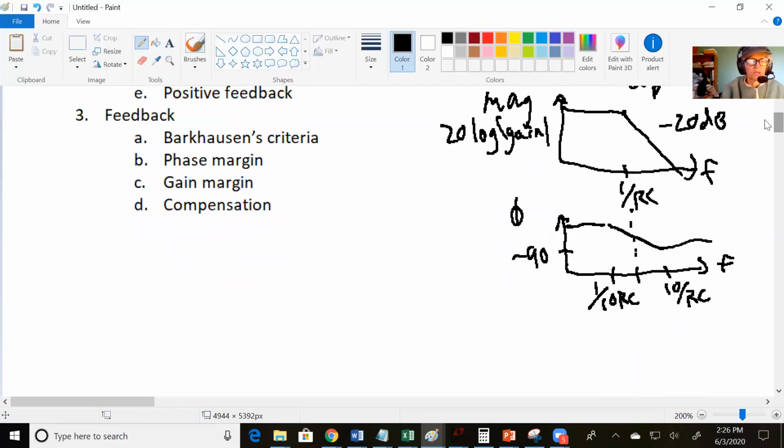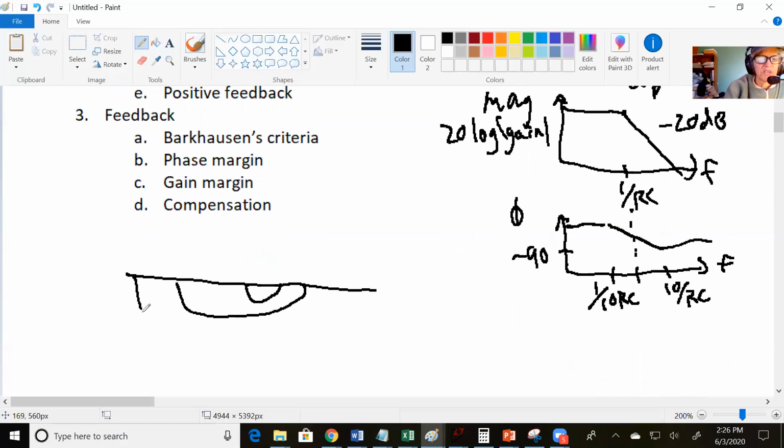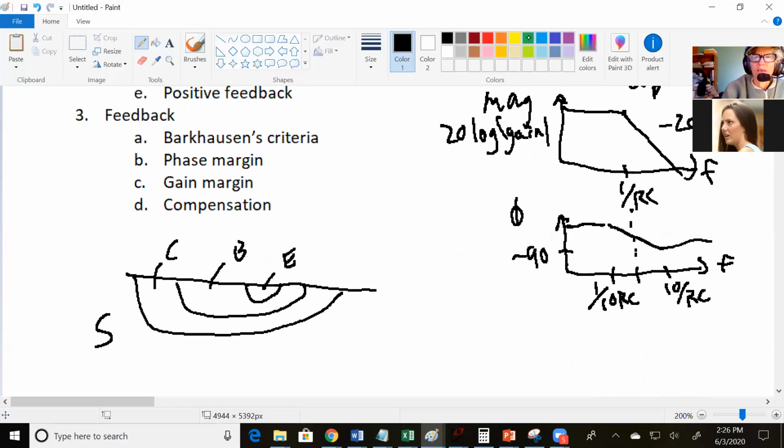Should I leave that visible? So let's do a BJT. I know I've been really BJT centric, but hopefully you can apply what we've looked at to MOSFETs as well. MOSFETs are easy peasy once you know BJTs. Okay. Got our 3 capacitances. So again, poles are easy. I shouldn't say that. You can use the quick method to find them. But zeros, again, you have to do small signal analysis. So you need a small signal model that includes the capacitances.